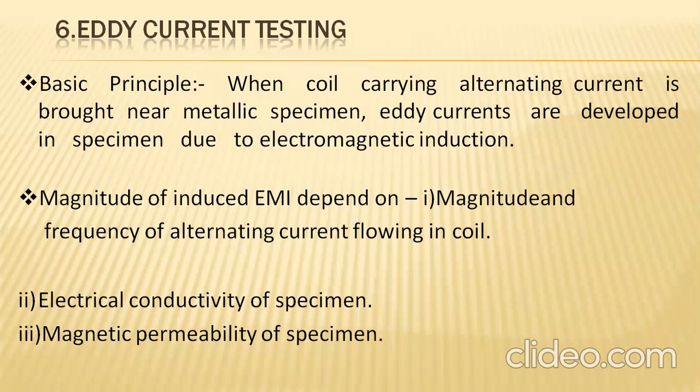That deviates the flux from its direction. So wherever a crack has been identified, the flux direction will change, because at that particular point the polarities will be different. Normally, we see a component with a north pole and a south pole. If a crack has occurred there, the polarities automatically become different at that particular point or crack area.